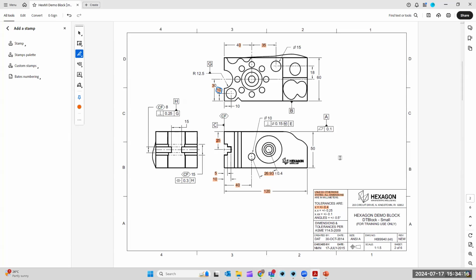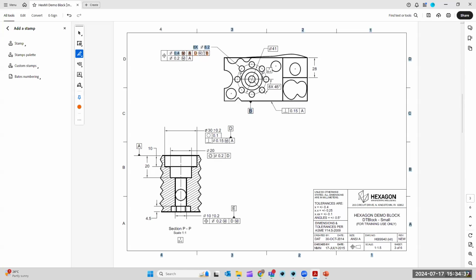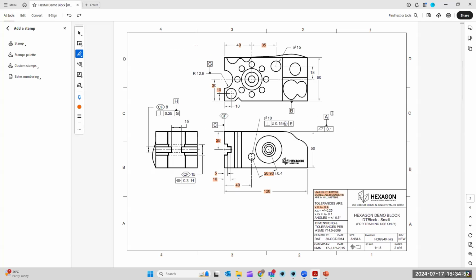Like my goal ultimately is to take this drawing and to measure the 25 millimeters, the 10 millimeters, the 30 millimeters, the 40 millimeters, the 35 millimeters. So I need to verify that all these values on this drawing are correct. But I don't know where to start. And I could say, okay, if I start with inspecting this whole pattern, I need to start with an ADB alignment. So it depends which thing you choose to inspect first on your drawing, as to what alignment you're going to choose to do in DCC.